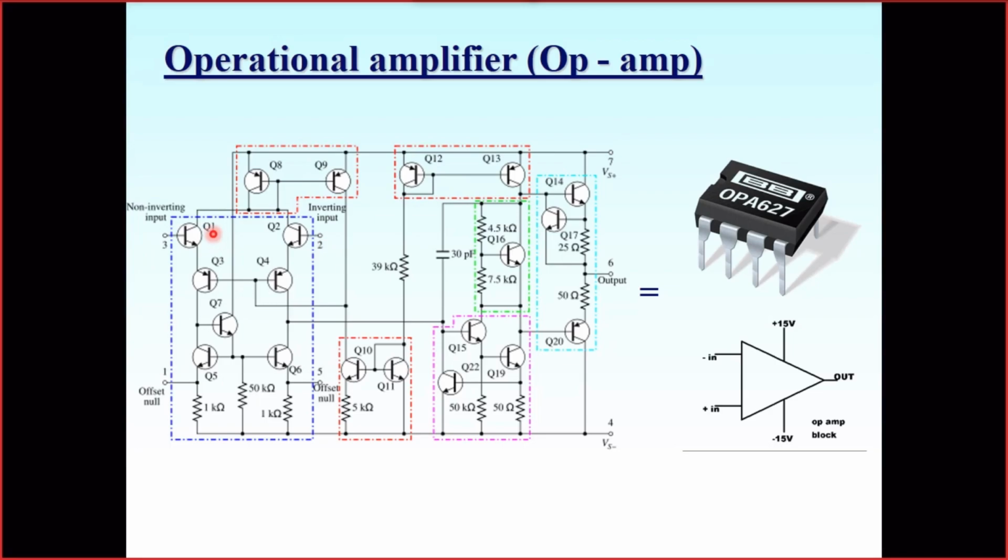Here you see the input stage of the amplifier is actually two current sources, one and another, which we control using the non-inverting and inverting inputs. When we apply some voltage to the inputs, a certain current starts to flow through these two lines and is transferred further to the next stage.